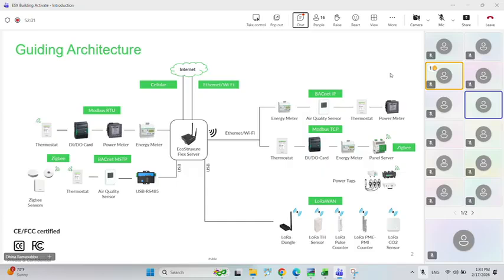There are two questions in the chat then. Node legacy. No. Yes, Fadi, it won't support Zigbee directly, so we have to use the panel server. Whichever device we configure in the panel server, we have to create a Modbus TCP/IP template. Through that template, we integrate the devices with the Flux server. I will walk you through those templates also; we can see that in later slides.